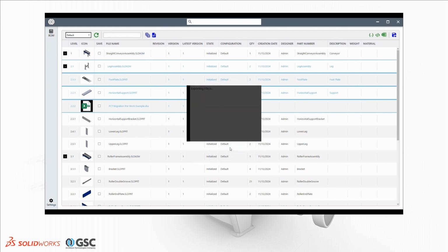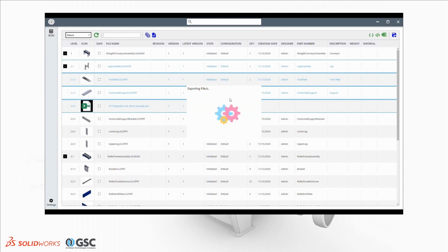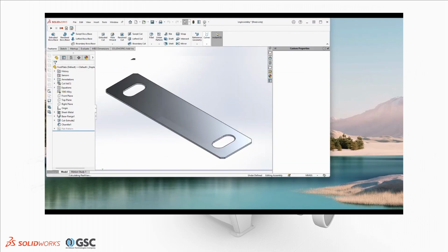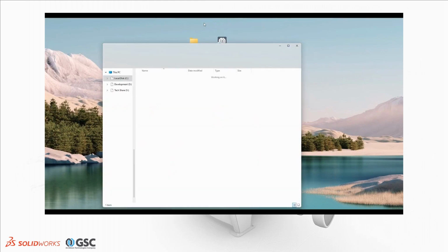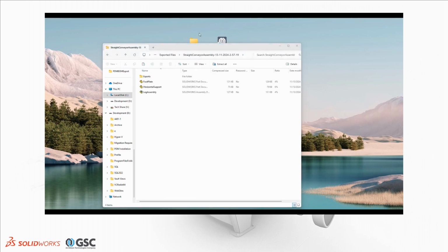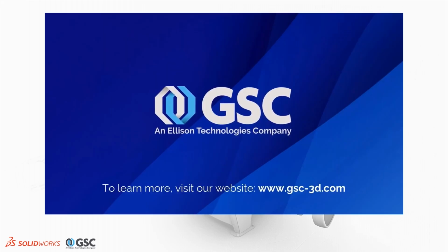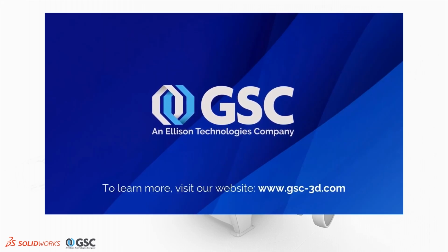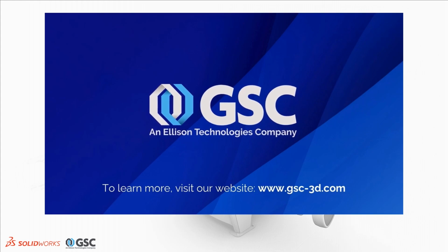After choosing an output location for the vendor spec package, SOLIDWORKS will open these files in read-only and save them in a zipped folder in the export location. Inside of the zipped package, you will see all the files and file types you selected during the export. Utilizing CADBridge throughout your daily workflow helps your users reach PDM's full potential.